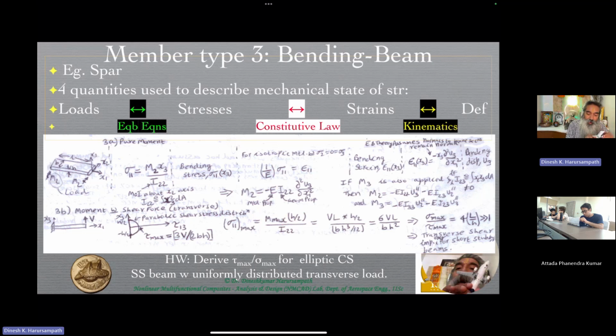In the case of the aircraft, indeed that is the case, because there's a lift distribution like this, an elliptic lift distribution, and there's an accumulation of the bending moment coming from the tip, which has a zero bending moment, all the way to the maximum bending moment at the place where the wing is attached to the fuselage.